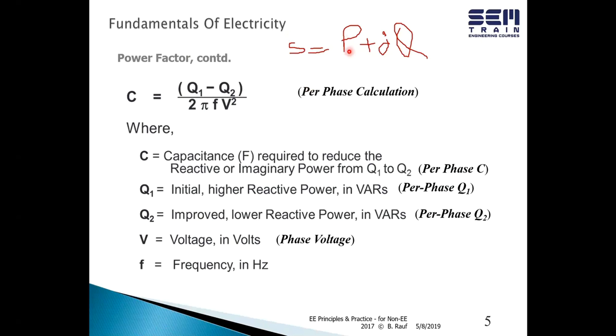Well, power factor is defined as the ratio of P over S. So if P is staying constant and S is going up because of too much inductive reactance, what's happening to the power factor? It's going down because the ratio of P over S is going down. So that's another way of looking at the dynamics of power factor. And if you understand the dynamics of how power factor goes down, you can better understand the dynamics of how you remedy it, and can better understand power factor related problems and work them easily. And you can pretty much rest assured you're going to have multiple power factor related problems. They may not be exclusively power factor type of problems. They may be problems that entail complete understanding of power factor. So that's why this topic is of high value, even though we don't have many slides injected in here for it, specifically in this section.